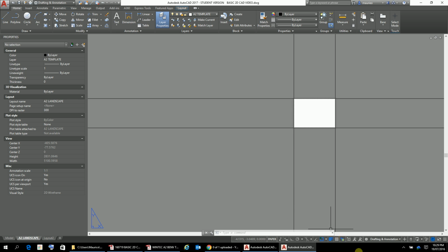Now those little object snap things, see this blue box down here, that's the object snap, so that's turning it on, and if you click in here, these are the settings. So these are the little ones there. There's an endpoint as a square, a midpoint as a center, a node, intersections, extensions, perpendicular, nearest is that little one I showed you, and apparent intersection. So they can be turned on and off. You can turn them all on and off here by just clicking that, or you can also click F3 and that toggles it on and off, but it only works in a PC situation.